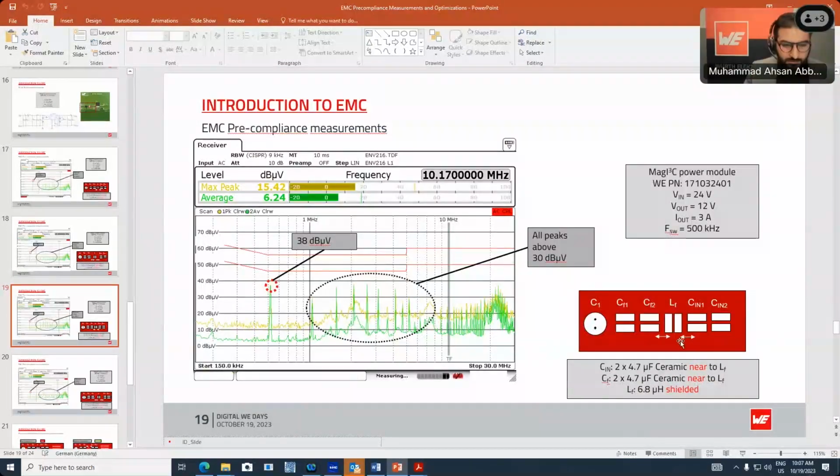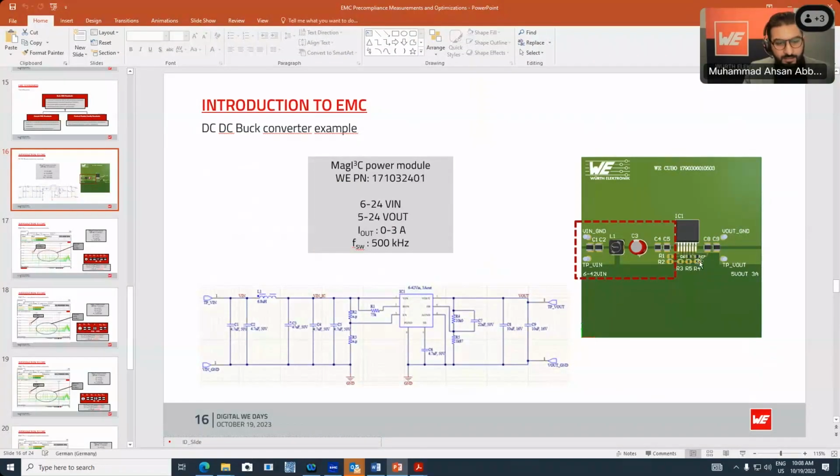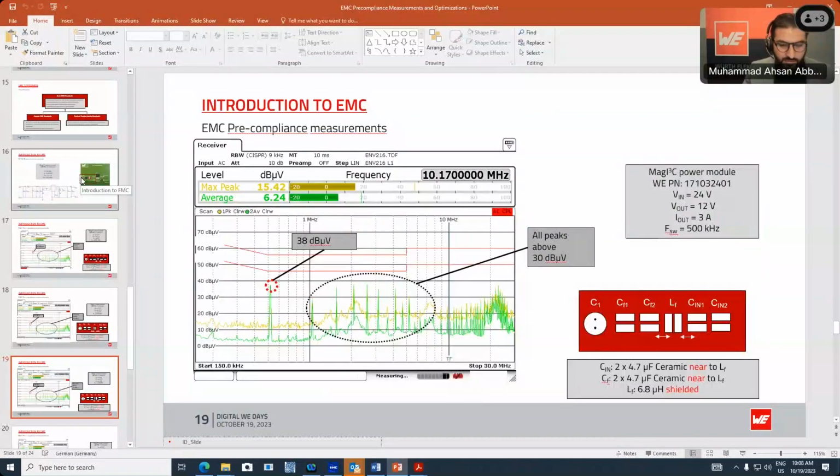Millimeters is already, I would say, a big range. This is more or less hit and trial. I used this in the designs we show for all the evaluation boards, but in a real application, this is an interesting question, because you have more flexibility to place your components around the DC-DC converter. You don't always follow a horizontal style of placing components in line with the converter, but you have a bigger PCB and more flexibility to move your components around. So it's normally hit and trial, but around 1 mm or less than 1 mm is always okay when you are not too close.